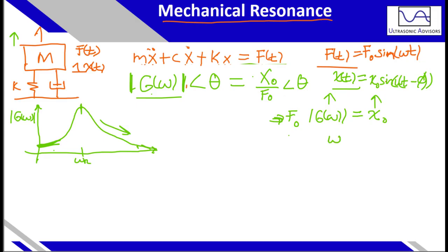So in general, this relationship exists where you have your displacement amplitude multiplied by the frequency squared equals your acceleration. So the acceleration keeps getting higher and higher, which actually provides an opposing force for that mass to move. So you actually have lower and lower displacement as you increase frequency.